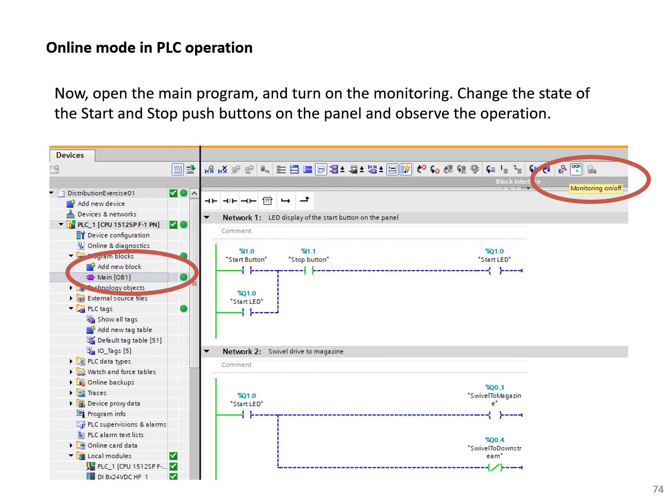So in the real device, if you click on the start, then this one will go to the solid green, as you could see on the stop, because this stop button is a normally closed contact, but this one is a normally open. But in the PLC sim, you don't have access to the device. So how could you change the status of this start button? You just right click on this contact, choose modify to, for example, 1 or 0, and then you could change the status of the contacts in the simulation.